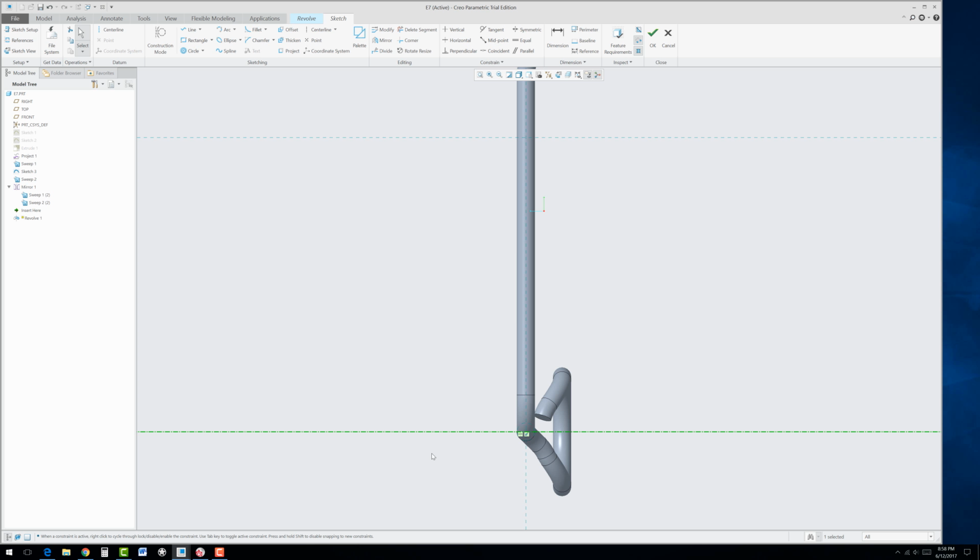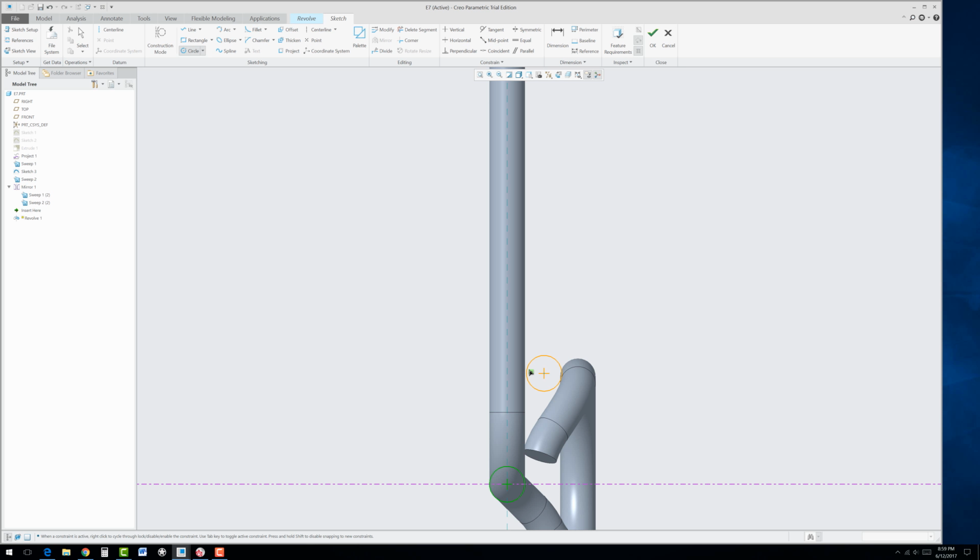Okay, now we could go ahead and go to the circle tool. Now what's really neat here, just go to center and point, and between these two pieces of material, just find yourself between them and click and drag out a circle and let it snap to equal. See that little equal symbol right there? When it snaps to equal, look at it, it's making it equal to our reference geometry. So everything is going to be 1/2-inch diameter wire. I know you're thinking, well, that's a huge muffin fan. Yes, it is. I just like using the even numbers. Okay, middle click, and now let's go ahead and change some of these things.